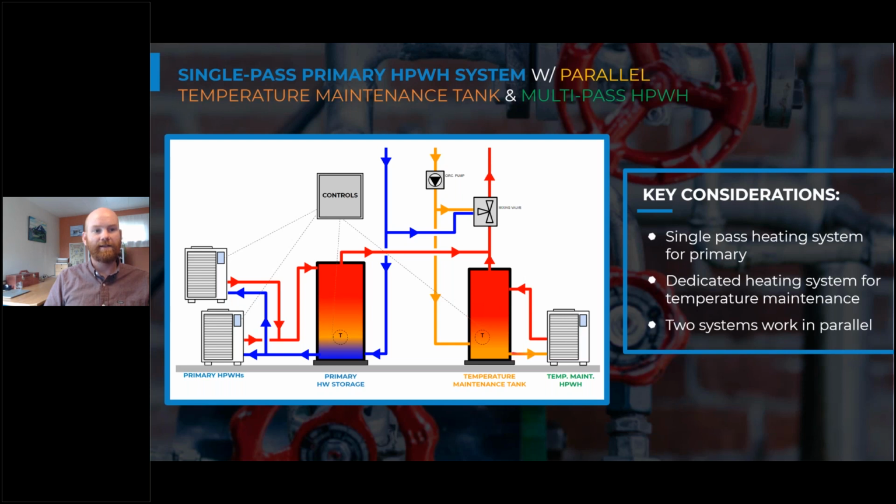And so that reheats that 110 degree warm return water back up to 120, and then it starts pulling in 125, heating that up to 135 towards the end of its cycle, so that we're mixing hot water out at about the same temperature as we're storing in our primary storage. This gives a consistent temperature on the hot side of that mixing valve.